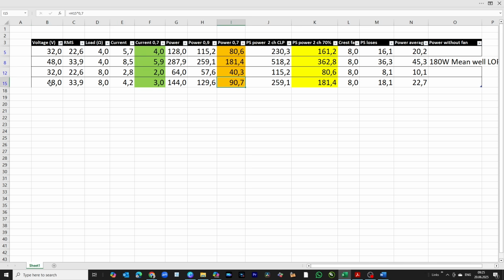Yeah, and then those power supplies are capable of some extra peaks, and good large capacity electrolytic storage capacitors on a board help to get confident calculated loads. So this is a maximum. Don't believe those 300 watts that you have in promotions. The theoretical maximum for TPA3255 is 200 watts per channel. Great, excellent, 200 watts per channel on a 4 ohm load and 100 watts on an 8 ohm load.